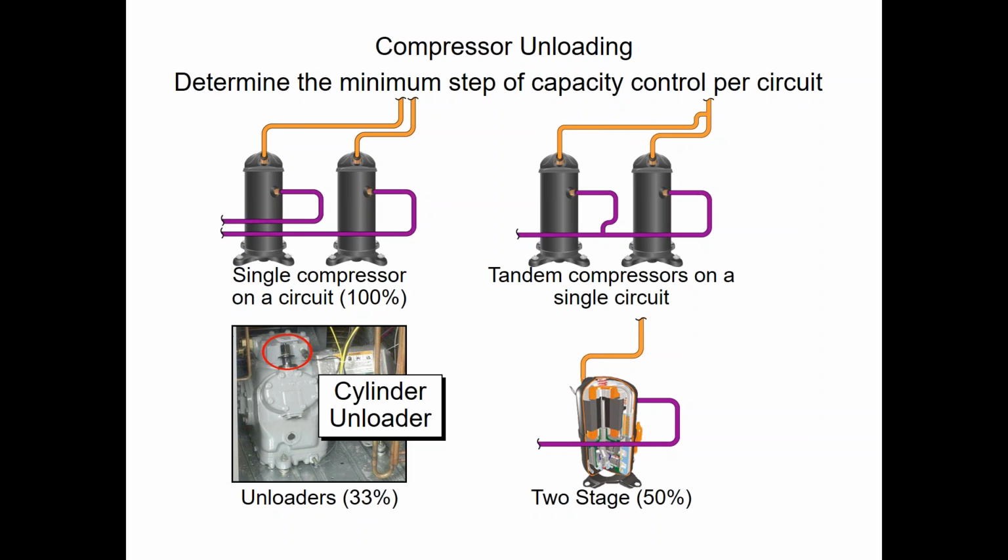Okay. So the way you figure out what you have is you go into the product data, and you can look at your compressor model number and the associated tonnage with it. But most of the time on the small units like that, it's equal split.